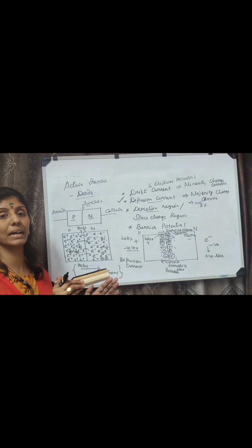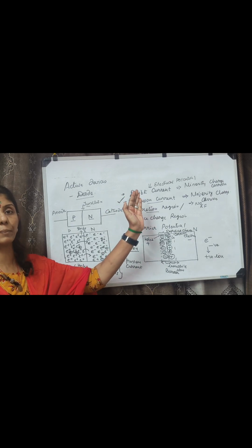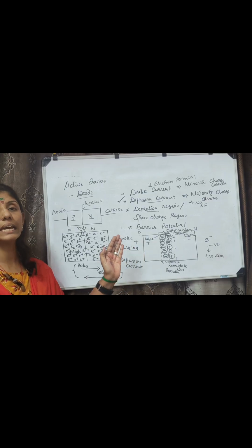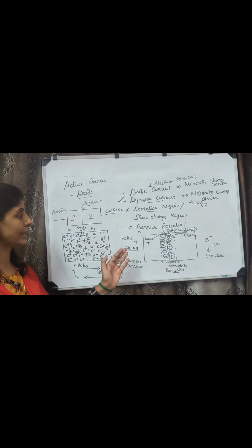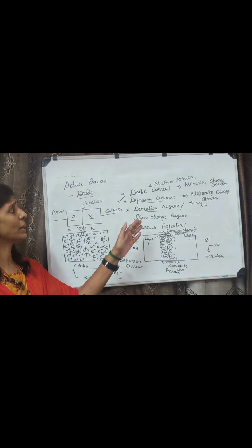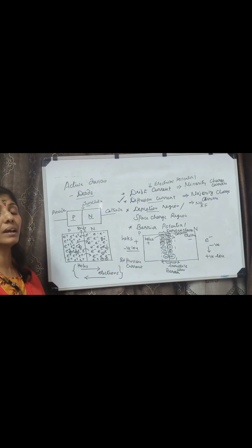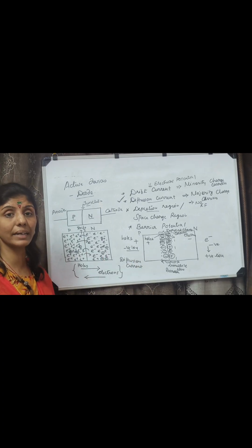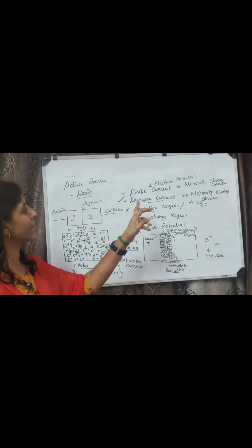Once a P-type semiconductor is combined with an N-type semiconductor, first the diffusion current will be produced, because the P and N regions should have an equal distribution of holes and electrons in both regions. Once that happens, automatically the depletion region will form. Once the depletion region is formed, it acts as a barrier. That barrier produces some potential which is termed the barrier potential. Okay, right. Already I said drift current.